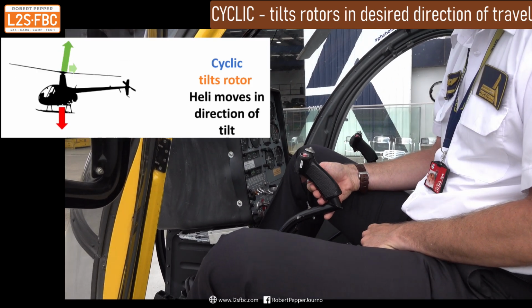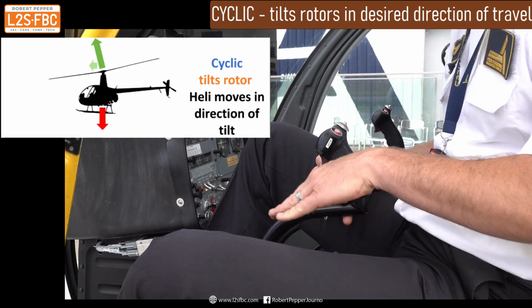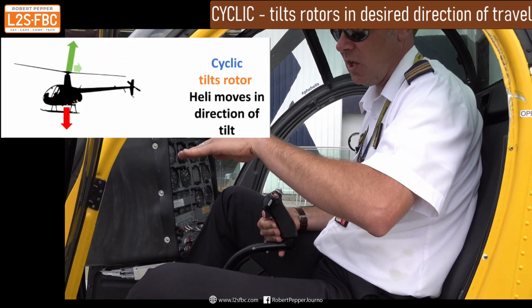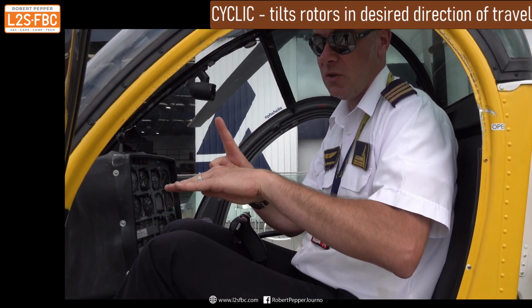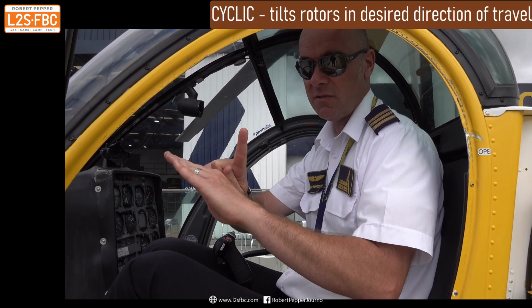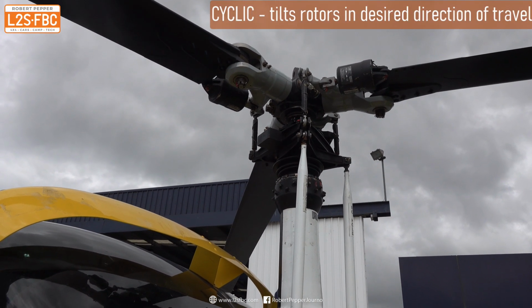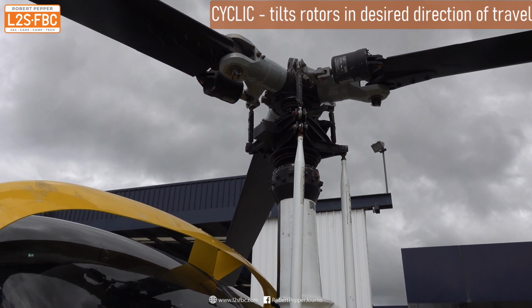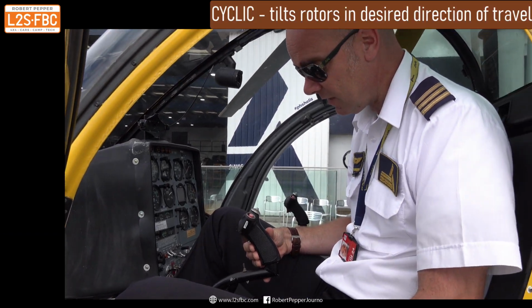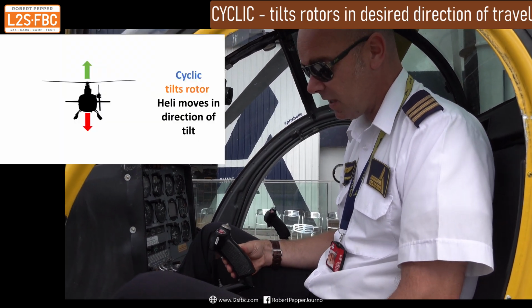The opposite is true as well. You pull the cyclic aft, the nose will pitch up, a nose up attitude. You'll slow down by redirecting that thrust that initially was forward. You slow down by reversing the thrust backwards. Depending how fast you do it as a pilot, you either go forward fast or slow down or even fly backwards. Yes, that's correct. In certain ways, helicopters can fly backwards. Put it back in neutral.